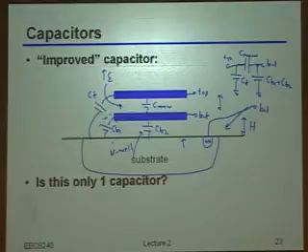Or rather, is that necessarily a good thing? Yeah, right. So remember, anytime you've got a P and an N, there's always a junction there. So that means there's always going to be this depletion region. Of course, assuming you've kept things reverse biased as they're supposed to be.